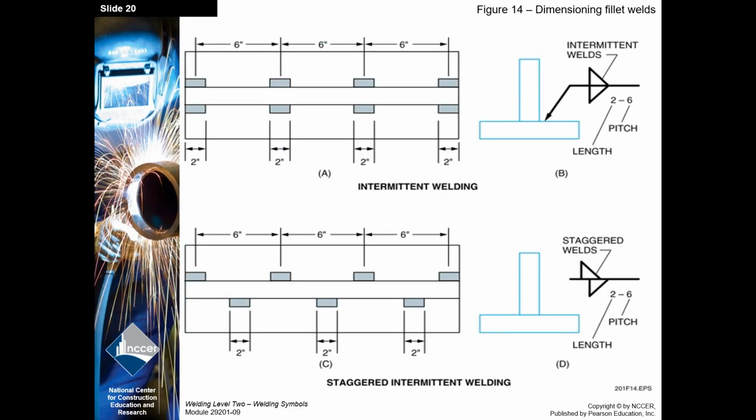All right, we have stitch welding, or skip welding they call it. A lot of different slang, I guess. We have intermittent, and they call this intermittent chain welding. So it's staggered evenly as we have it. And I shouldn't say the word staggered, because down here we have staggered, it's alternating. So staggered intermittent versus regular intermittent. And this is a way to reduce the heat, the stress, the distortion, or in some cases it's just a waste of time and effort to weld it all.